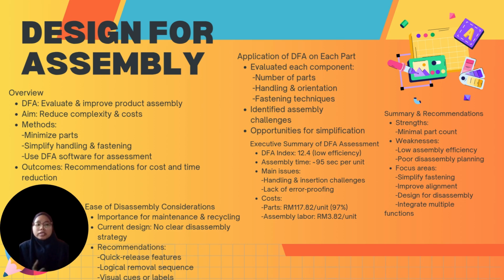We also consider ease of disassembly, which is important for maintenance and recycling. The current design does not include a clear strategy for disassembly, which could make servicing more difficult. To address this, we recommend adding quick release features, arranging parts so they can be removed in a logical order, and using labels or visual cues to guide disassembly.